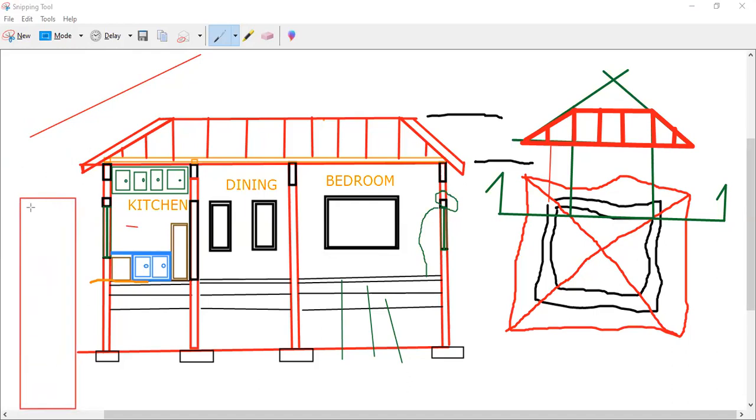Say this is my wall, and that is my ring beam. I would typically draw the wall in AutoCAD at the location, then left click, then grip the middle and drag it a little space inside here, because you want to ensure that this cuts, it creates a notch.